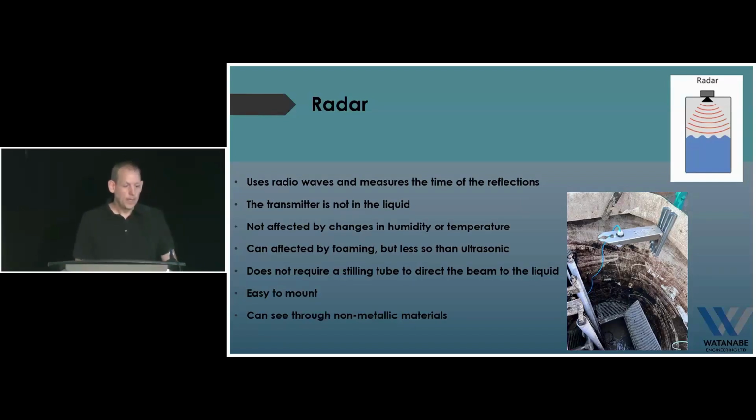So with transmitters out of the liquid, you can set these things right at the top of the well, right out of the way. So even if you get the occasional flood or high level, they don't get affected by that. And they're not affected by humidity or temperature, the same way that ultrasonic is. So the radio waves, because they're higher frequency, just punch through all of that stuff. They don't have that same effect.